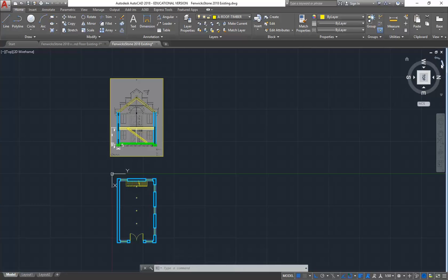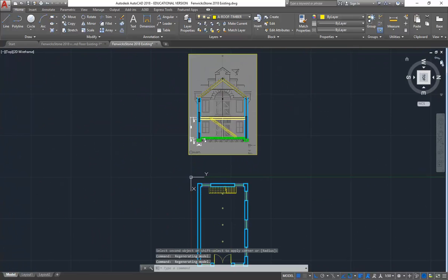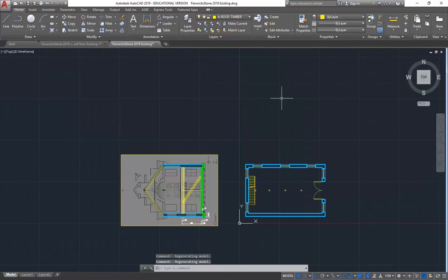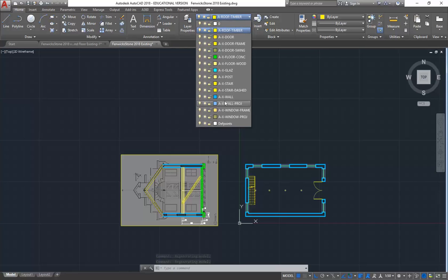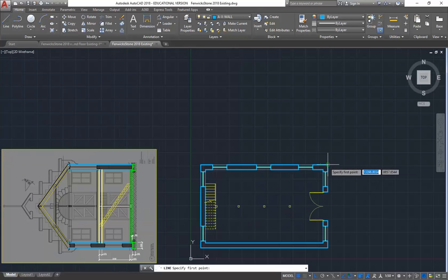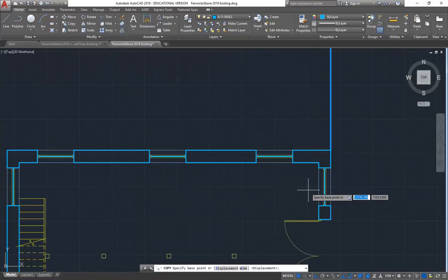So I'm going to use that option I showed you last week in the top right corner to rotate the drawing. And so I always get these mixed up. Those arrows are back to front to me. So here I'm going to use the top left arrow, or the one that's rotating anti-clockwise. And then I'll just draw a few lines as we did before to project off my section vertically. So I've got ortho on, so I can just draw straight lines going up from the wall there. And again, just to save time, I'll copy that line across.